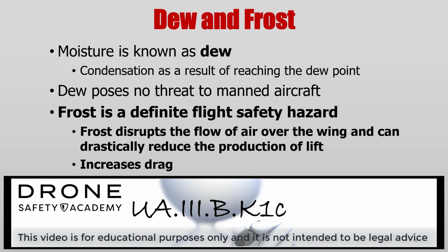Dew is moisture that has condensed as a result of reaching the dew point. Dew poses no threat to manned aircraft. However, that may not be the case for all models of drones and SUAS. Those electronics may be susceptible to condensation on a small aircraft.